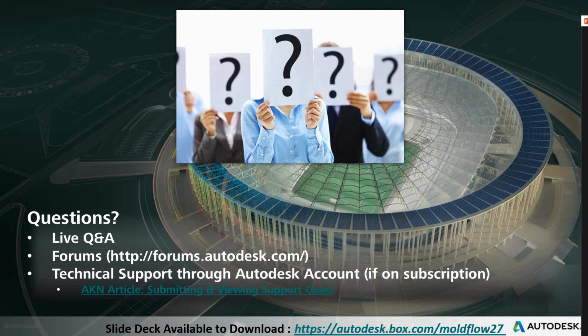Beth, yes, I could see one question: can parametric studies and DOEs run on a Linux server yet? So I will say yes. One of the limitations that we had before in Linux was that we were not able to run meshing. But since, I cannot remember which release in 2017, we are now able. So I will say yes, it should be possible. But we could check that, and if it's not, we could just post it in our forum.